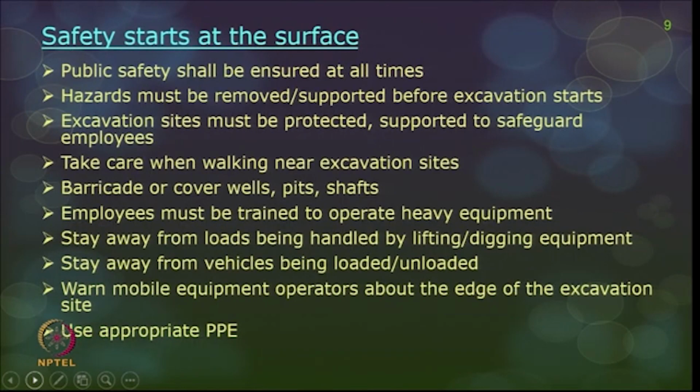The hazards must be removed or supported before the excavation starts. Excavation sites should be protected or supported to safeguard the employees, and take care when you are walking near excavation sites, because with the movement of vehicles, maybe with the flow of water, or maybe with the dump of soil close by, the land may be slippery and you may slip or trip and fall.